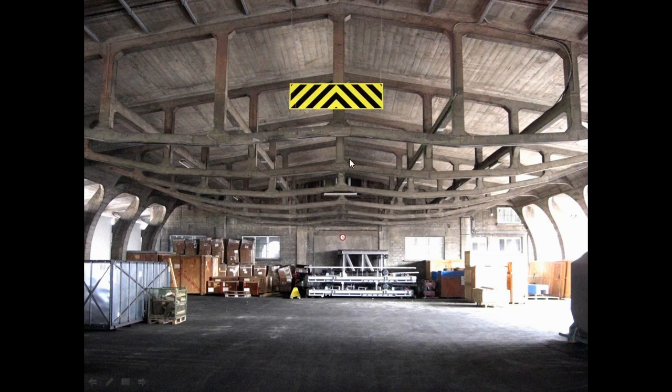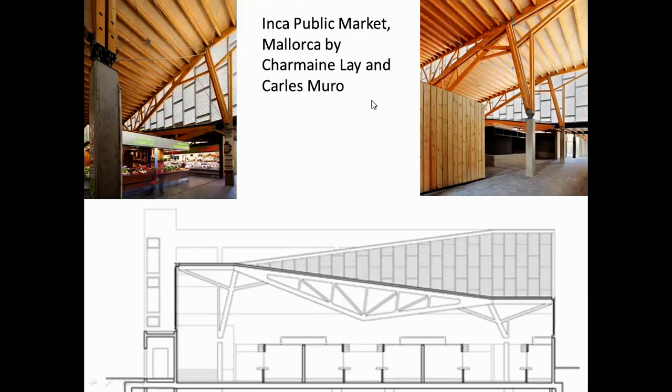This overall shape is actually what structural engineers call the bending moment diagram for the whole building. And the same with the columns. Look, the columns are just tapering just to solve the problem of that lateral load in the structure. So instead of a deep column, as in the earlier drawings that I showed you, this is just actually tapering slightly. So that gives you the diagonal that braces the whole. It's a very elegant structure. Here's some rather nice timber trusses.